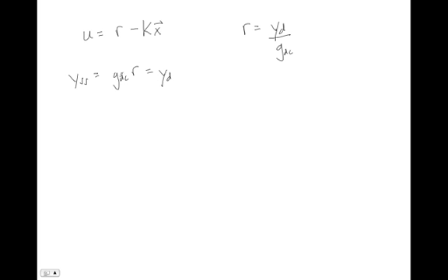It worked really well, and we said this works provided GDC is not equal to 0. In the case of a DC gain of 0, this tracking problem doesn't really make sense, but as long as we're not dividing by 0, we're going to be fine and this will work. So this all makes sense if you're in single input, single output land, but we're not there anymore.